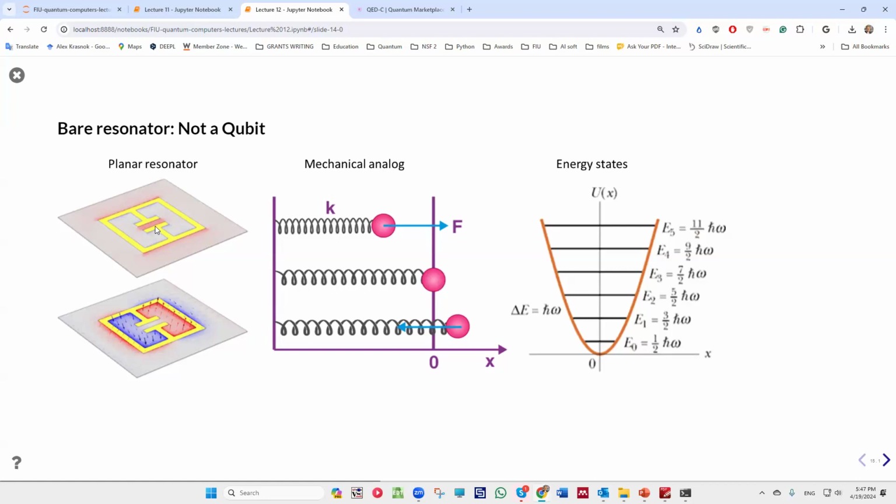It stores the charges, right, for some period of time, and creates the electric field in this gap. In the next time instant, half of the period, these charges form the current that goes along these straight parts, and this current creates the strong magnetic field.